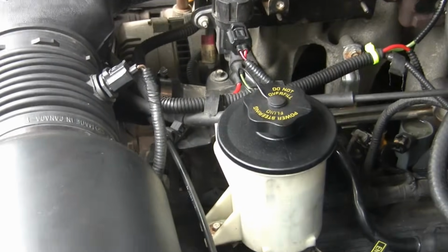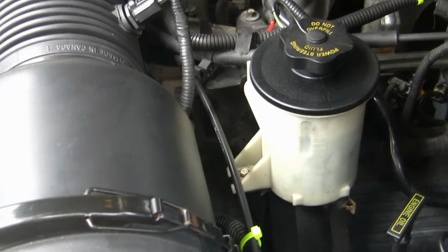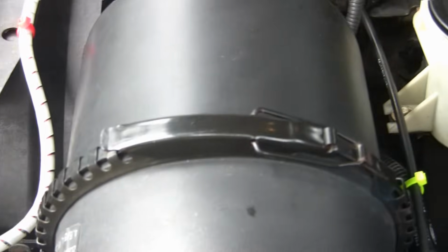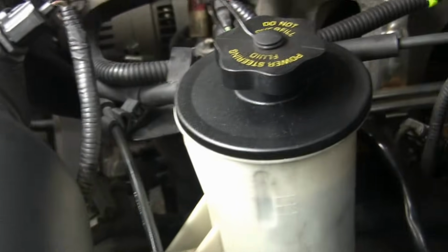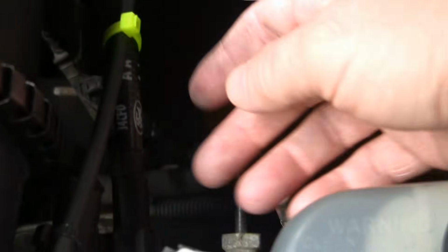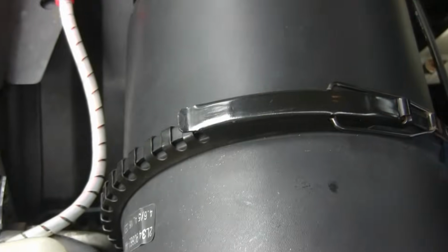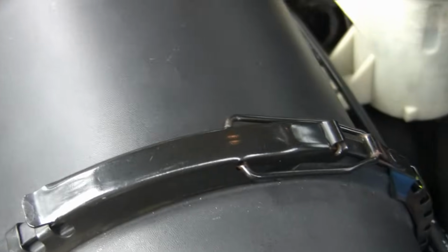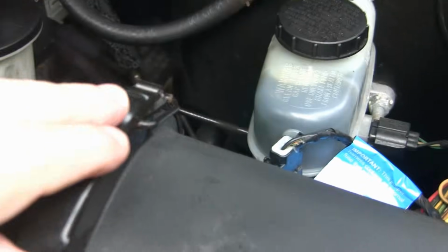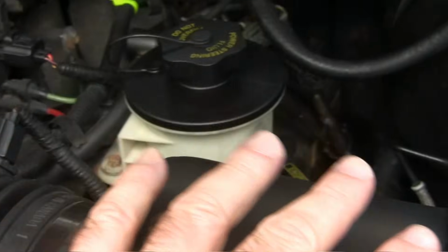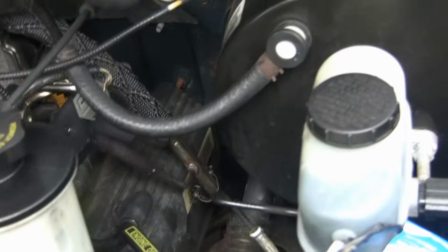Another tip for you, if your vehicle has quite a few miles on it, when you're messing with the EGR, you might want to check what they call the mass airflow sensor. And this is the actual wire for here. And it's on the underside of this air intake tunnel. And what you need to do is just unclip this guy. You can take a screwdriver, loosen this clamp. You can take this apart.